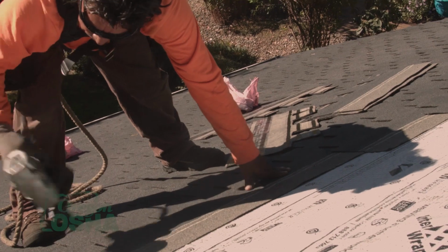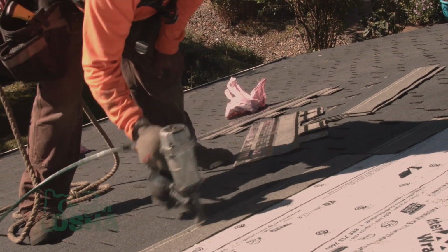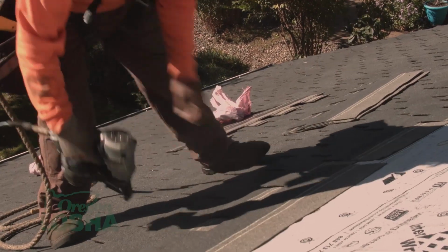If the companies that are involved in residential roofing really take a look at what the roof is, how it's laid out, and plan for their fall arrest so that they don't have swing falls off the gable ends. There are ways to set these systems up so that maybe we're working in more restraint than we are in fall arrest. Could it take longer to do the job than it would without having any protection? Probably so. Is it going to mean educating themselves and their workers to the hazards and how to properly set their systems up? Absolutely.